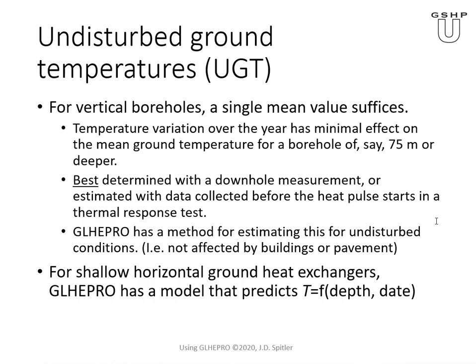GLHE Pro also has a method for estimating it if you don't have a thermal response test. The method is based on a model and a large database. And it's for truly undisturbed ground temperatures. So specifically here, one that's not affected by urbanization, by buildings or pavement.